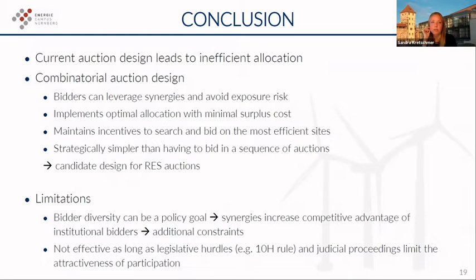Yeah, so if there's zonal pricing, then of course the incentives would be different. In a way, this whole auction design would not be that necessary, because there are different prices in every region anyway for electricity. This would lead to new incentives. For example, if the zones in the south would have a higher electricity price because there's less generation capacity available, then the incentives to build wind plants there are higher. In general, but then there's also the system of the sliding feed-in premium, which kind of negates the incentive from the zonal pricing again. I don't know if Robert wants to add something to this, because he raised his hand.